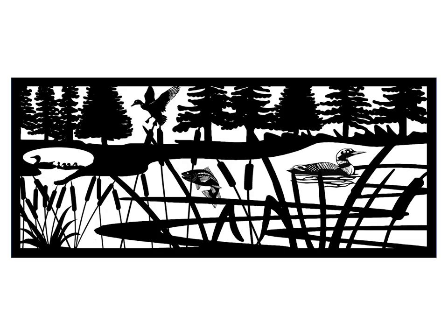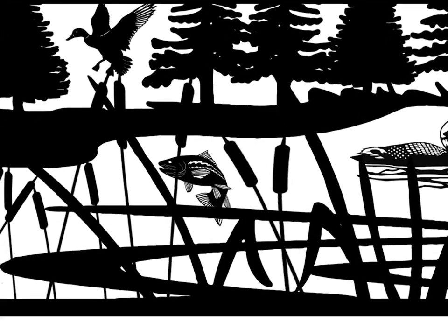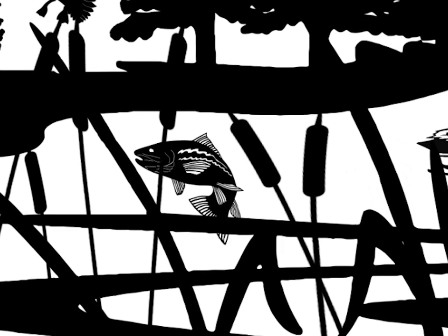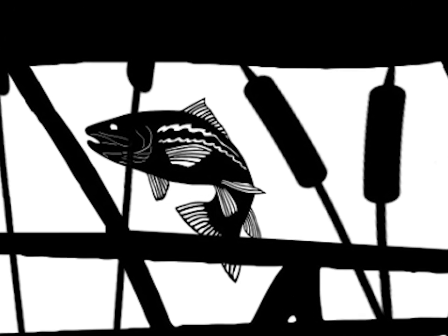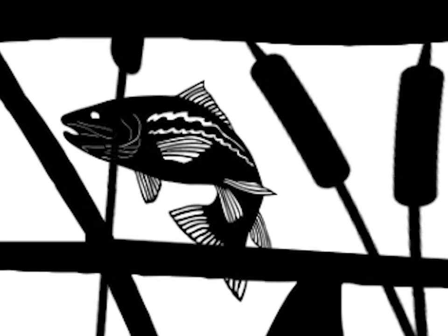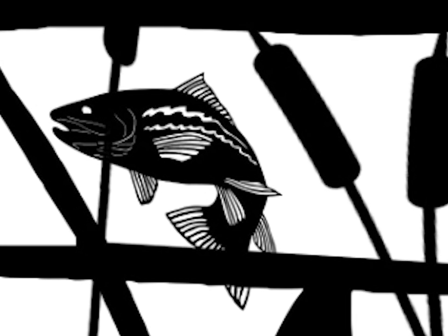There are companies that will take your design and cut it out of a sheet of steel. The cutting machines that they use easily import files that are drawing exchange files, or .dxf. A .dxf file is a vector file, which means that the drawing can be zoomed in or out and the quality remains the same. You can download many DXF files for free off the internet. Link is below. DXF files are also known as AutoCAD interchange files.